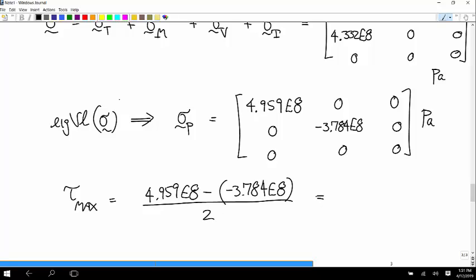And so the maximum shear stress you could have is 4.372 times 10 to the 8 pascals. If you have a very brittle material, then this would be enough to calculate whether it's going to break. Well, no one builds beams out of brittle materials, so actually calculating the yield stress would be pretty complicated in this case, but that's a start.